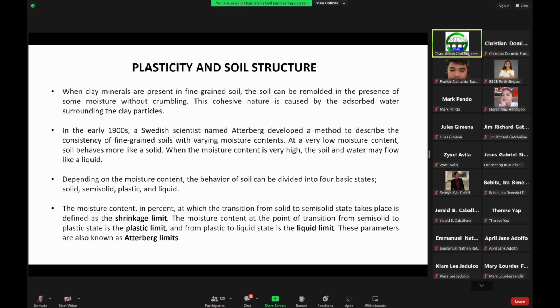I think one of you asked the question last time: what are the usual tests that we prescribe in a normal geotechnical investigation? Normally, what we prescribe is the grain size test, the grain size distribution curve. We require that grain size data.